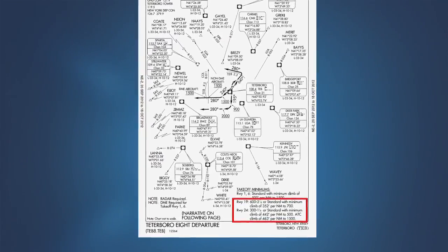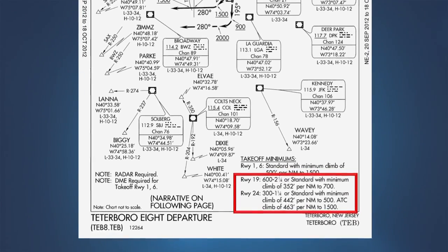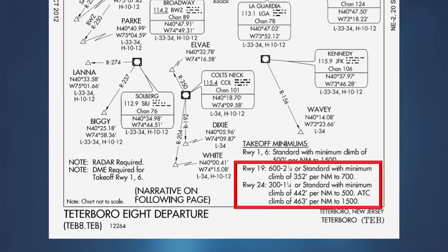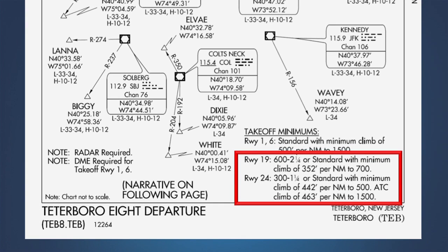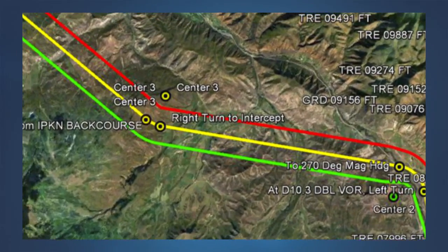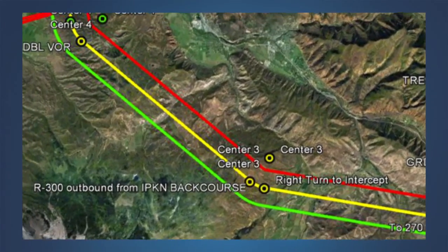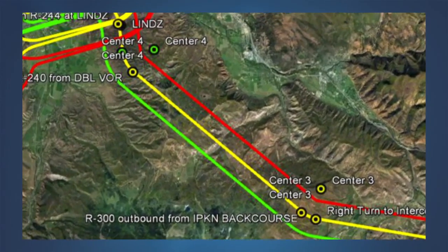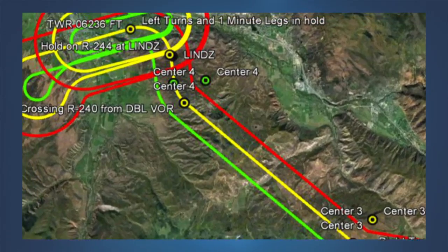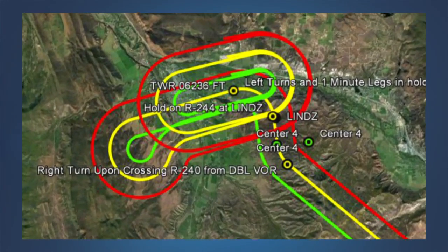These climb requirements are determined in consideration of all aircraft that are authorized to use the procedures and the full range of airspeeds that may be flown by departing aircraft. For example, 250 knots below 10,000 feet. On the other hand, the contingency procedures for an engine failure on takeoff are developed based on the demonstrated performance for a specific airplane type.